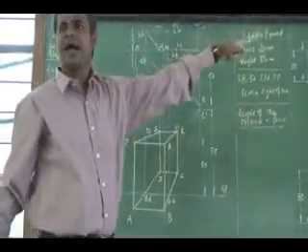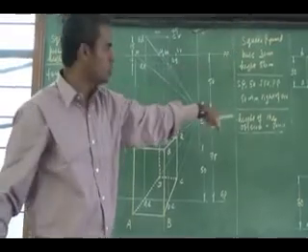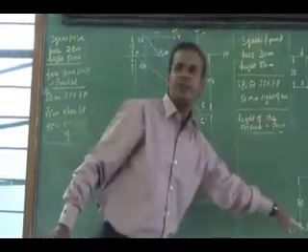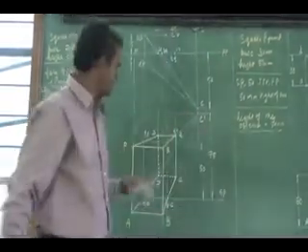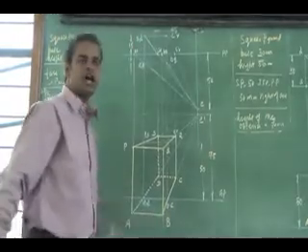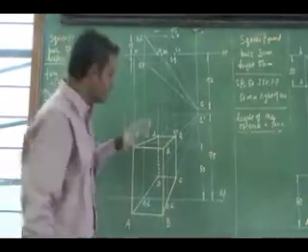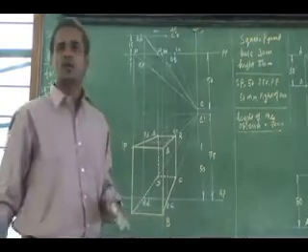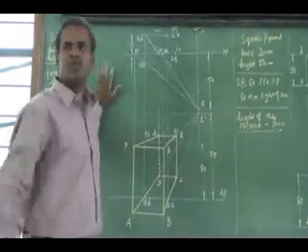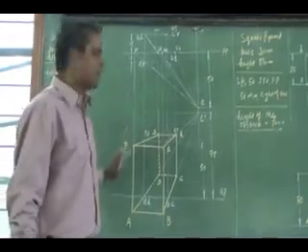Look at these three problems. The first one is behind, I have the reduced perspective. The second one, the edge is exactly touching the picture plane, I have the same size in my perspective, AB. Here, a small portion is in front of the picture plane, and that portion is enlarged in my perspective, so you leave a gap for that ground plane in this kind of problem, if you have some portion in front of the picture plane. Do you have any clarification?